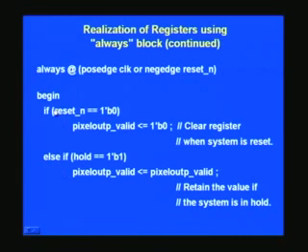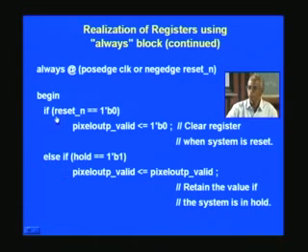You only get this by experience, so don't try to add more than these statements. If you are still forced to add more, you combine this outside the always block and then restrict this once again to 4 or 5. Smaller the number, better it is, and higher the speed of operation that you get.